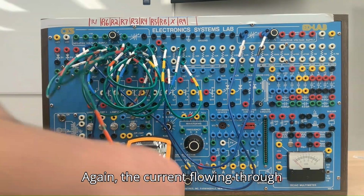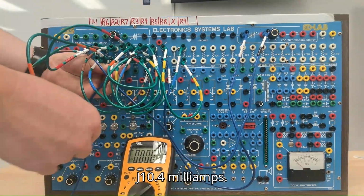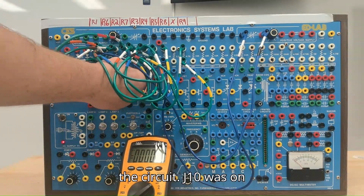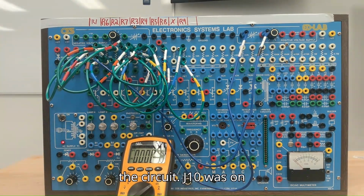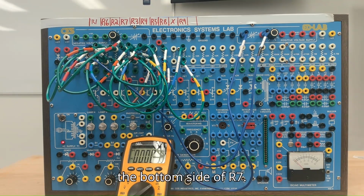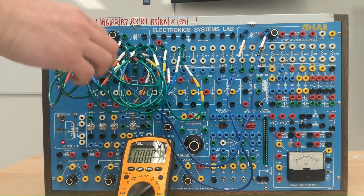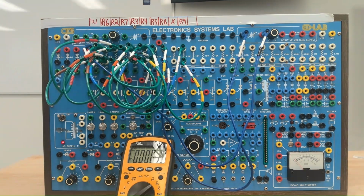Again, the current flowing through J10, 0.4 milliamps. We're going to reinstall J10 back into the circuit. J10 was on the bottom side of R7. Remove that temporary test lead, reinstall J10.